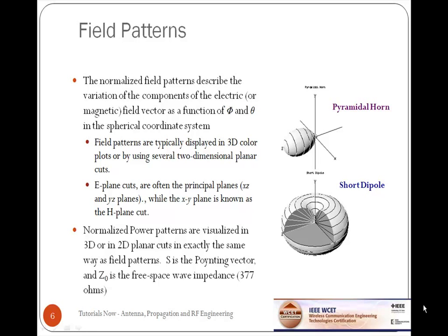Field patterns are typically displayed in 3D color plots, or in this case, shaded black and white, or by using several two-dimensional planar cuts. In the pictures to your right, which are the field patterns for the pyramidal horn and the short dipole, the E-plane cuts are often the principal planes, which are the XZ and YZ planes, while the XY plane is known as the H-plane cut.